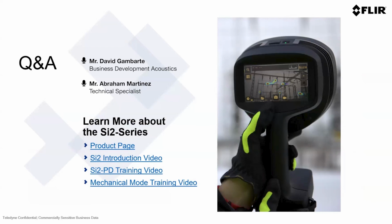Q&A: In a distribution line, we are using a thermal imager and an acoustic imager. Which do you think is more suitable to find faults and for troubleshooting overhead and underground distribution lines? As David mentioned, thermal and acoustic imagers are a great bundle together. For underground distribution lines, of course, acoustic emissions are not propagated through that medium, so in that case we cannot use the acoustic camera.